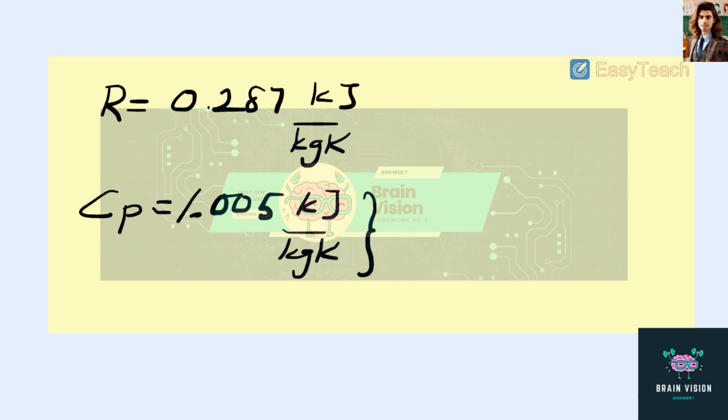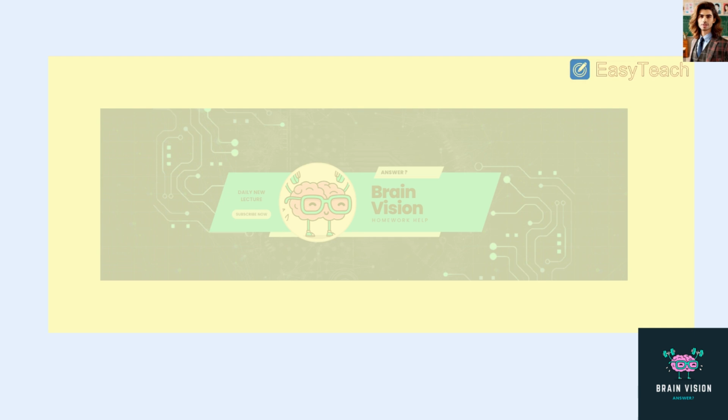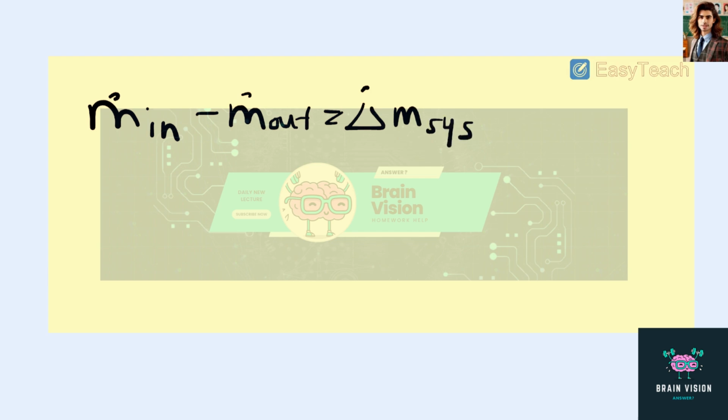Next, we're going to define our system. We're going to define the pipe as our system, because the mass is crossing the boundary of that control volume. So when we do our mass balance, we'll see that the m dot coming in minus the m dot coming out is equal to the change in m dot of the system. Recall that we are assuming that this process is steady state, so this change in mass of the system is going to be 0. Therefore, we can say that m dot in is equal to m dot out.